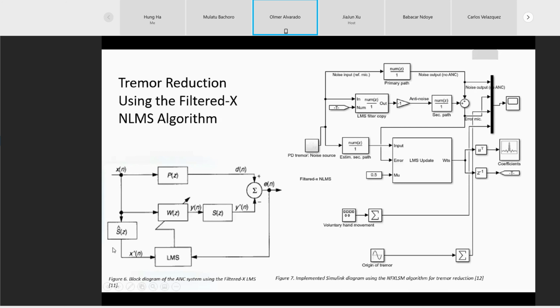And so the main objective of active noise control is that an anti-noise is introduced and designed to cancel an unwanted noise. This noise can be any disturbance, and for the scope of this project, we can treat it as an unwanted vibration. The reduction of the signal can occur if the signal and the anti-signal have the same amplitude, but opposite phase.